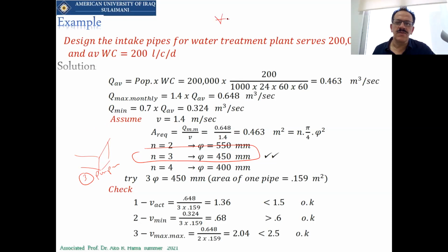I want you to find the volume of this sump. How to find the volume? You have the Q, this is the design Q. This Q design times 2 minutes, or Q minimum times 5 minutes, you will find the volume that's really required. And when you have V, you have to check for the B. B will be between 1 to 3 meters.